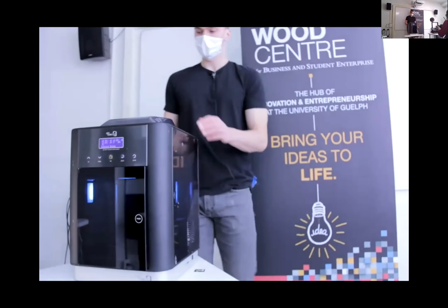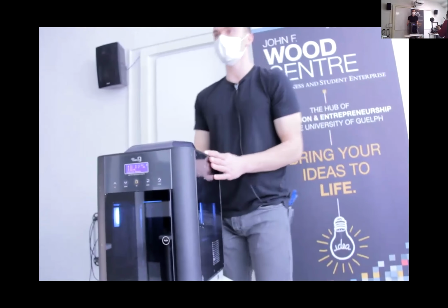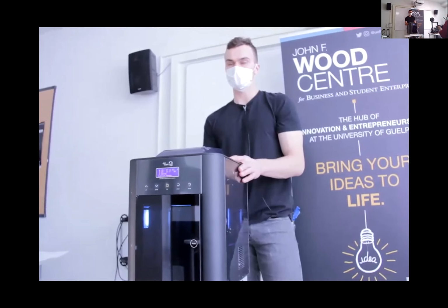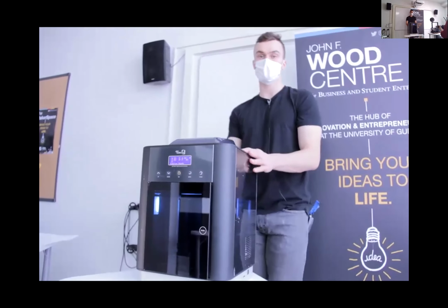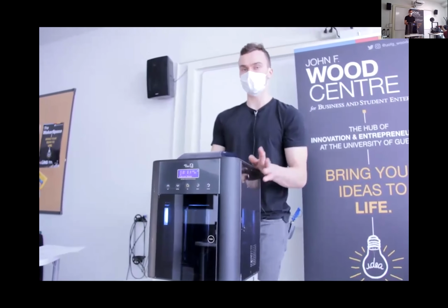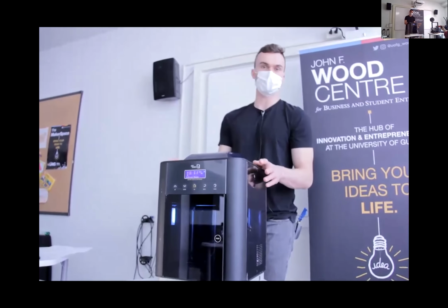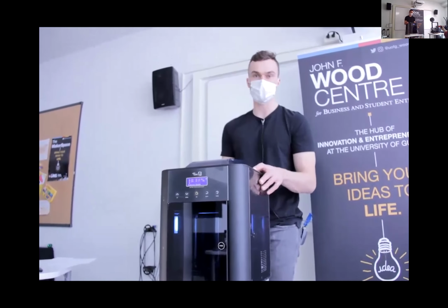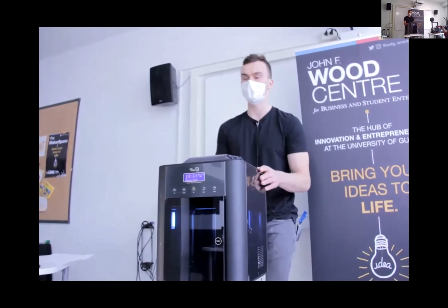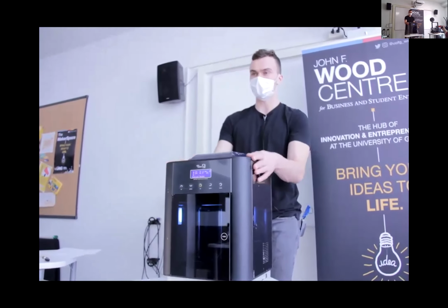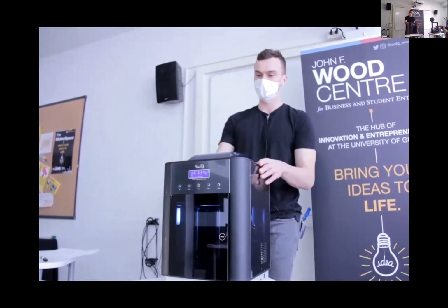Okay, so like you can see, it's very similar to the other printer, except that it's enclosed. The enclosure has some pros and cons. So pros being enclosed means there's greater temperature control. The ambient air temperature has less effect on the print. So if we're printing in a cold environment or a breezy environment, it might be better to use a printer like this, which is great.